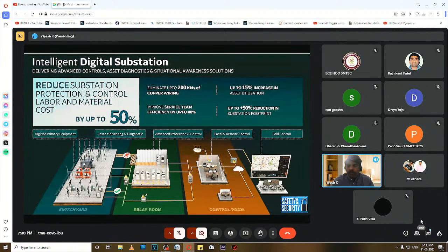In terms of monitoring and controlling a substation, you need to measure it, monitor it, control it and protect it, and use that data for maintenance or any further improvement you need in the network. So in this concept, how are we going to digitize? We digitize the voltage measurement and the current measurement using sensors. These advanced sensors use different technologies to convert it to a scaled-down parameter. Of course, instrument transformers are used mainly to scale down, because it can be 400 kV, or possibly 1200 kV, or 33 kV.